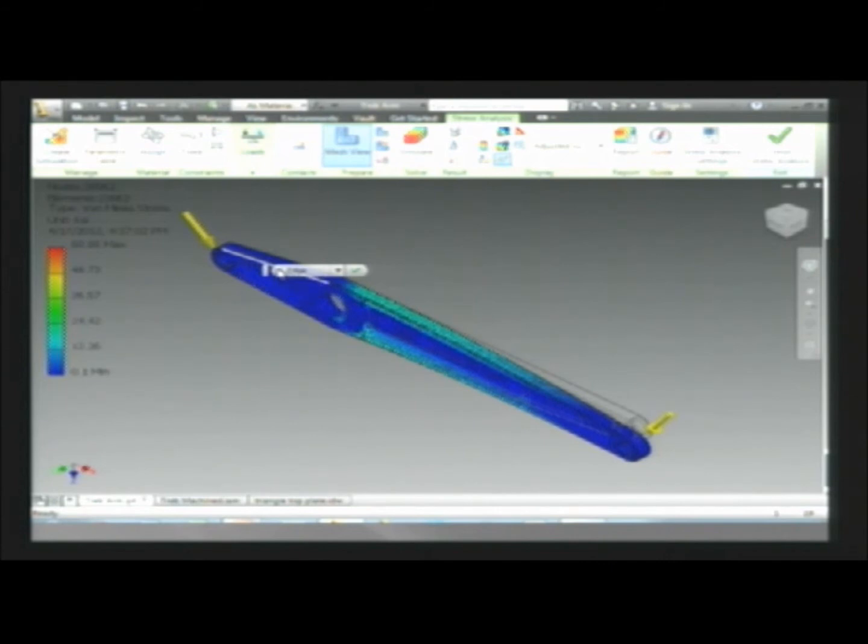Now as you can see, as it's bending here, you get the scale over there with how much pressure it can withstand. At red, it turns to a breaking point, but right now, it's in the blue. For this, I set up the center to be constrained, which means it won't be moving on the center hole there. And with 200 pounds on each force, this part would stand up fairly well. It would bend a bit, but it would not break.